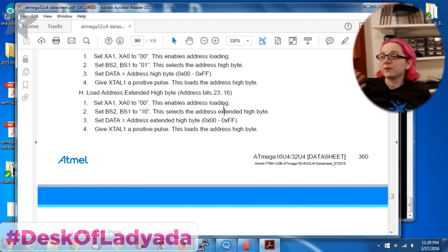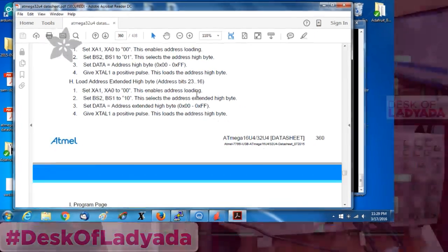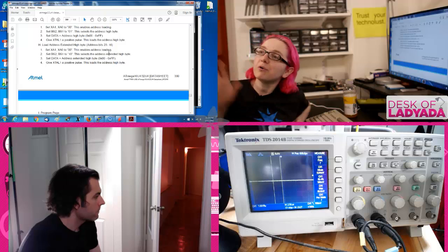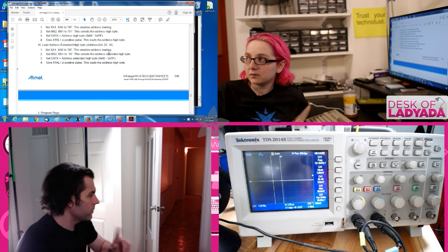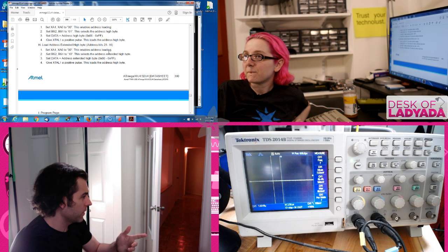The AVRs have very similar stuff. And then you can look at AVRDude. They kind of figured this out. They have the settings for each chip, slightly tweaked for page size, but the overall commands are the same. Erase chip is the same for all. Do the chip manufacturers do kind of the same thing? Can you kind of guess?